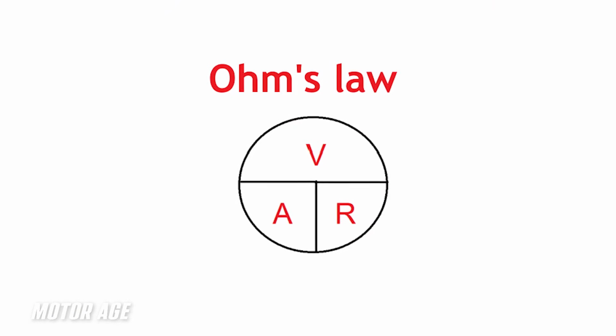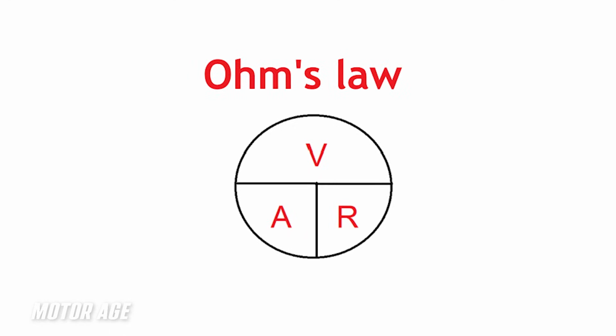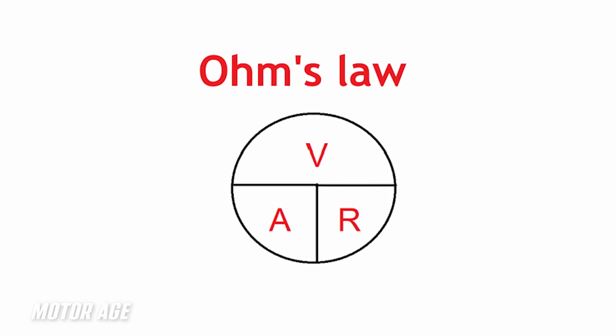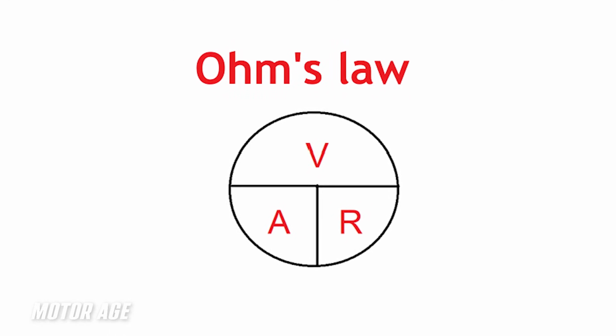And when I say that, I don't mean the written down paragraph version of Ohm's law, something you read in a book and attempt to memorize. That didn't help me fix cars. By truly understanding what Ohm's law means, the relationship between resistance, current flow, and voltage being electrical pressure, current flow being the movement of electrons through a circuit, much like water through a pipe, and resistance, the opposition to that current flow. All three of those angles relate to one another and allow us to develop anticipation on what we should be measuring, depending on how the circuit and the components within that circuit are behaving.